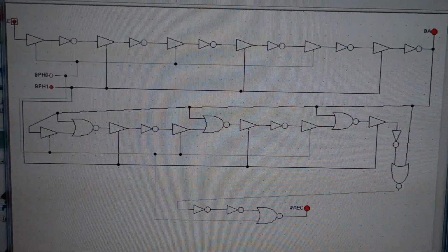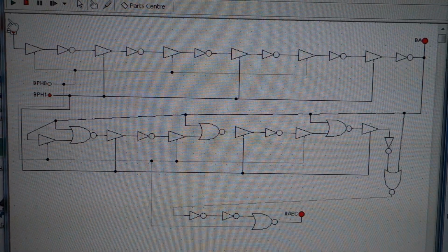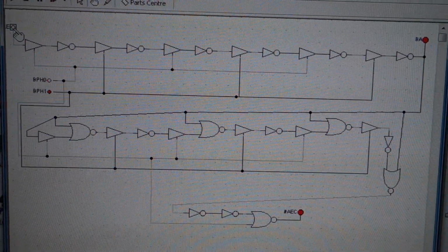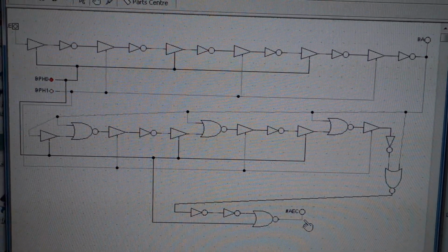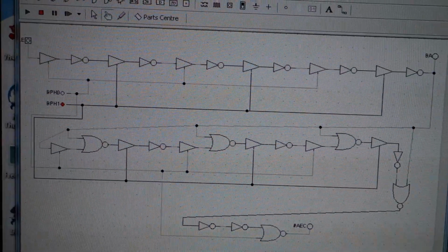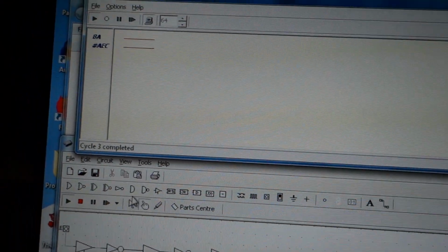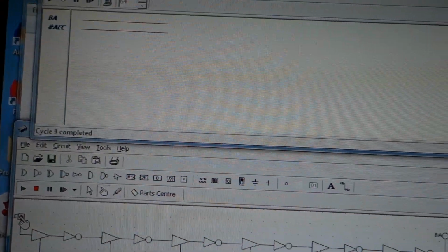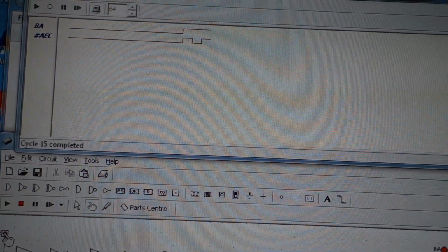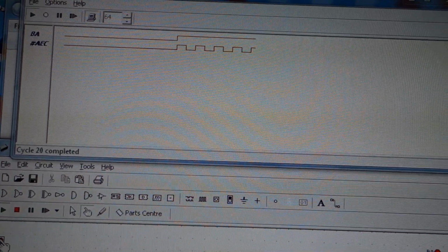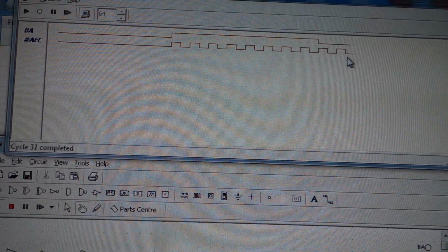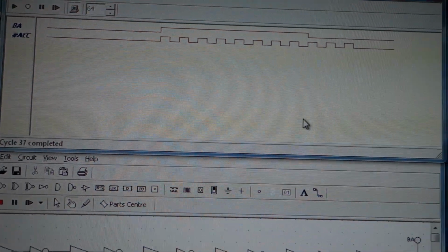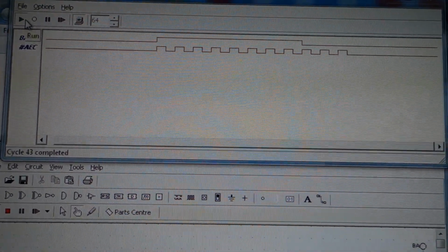And this follows in this panel. You can see it here. I could show you, but it takes so much time. So basically we can try and see what happens. When this one goes low, this one will go low there, and it starts blinking. This is hard to follow, so it's better to look at the history. So now it's running. Let's turn it high. There it goes high. It starts pulsing right away. Let's take bus available low. There it goes low, pulses 3 times, and then stops. Then the VIC has the CPU.